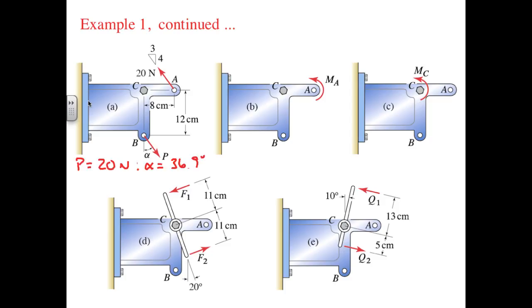We can use either the vector or scalar approaches to find the moment of the force couple. As this is a 2D problem, the scalar approach will be feasible, but one small adjustment will help us get the answer more quickly. Instead of analyzing the force couple as is, we'll break it into a force couple in X and a separate force couple in Y.